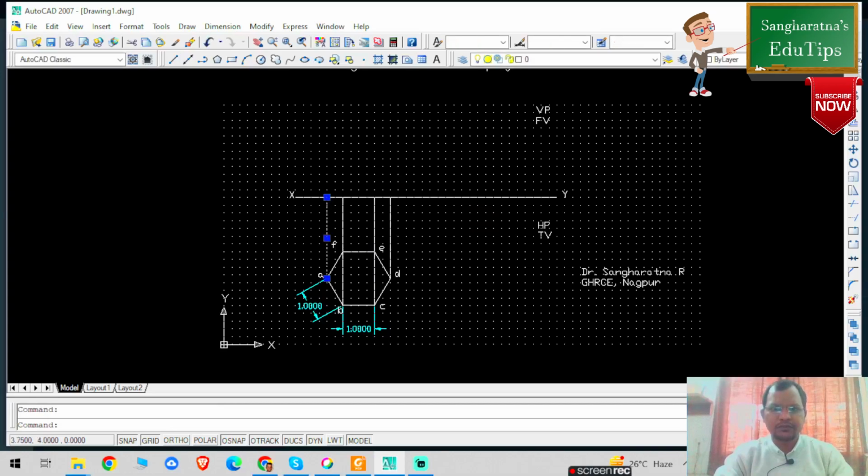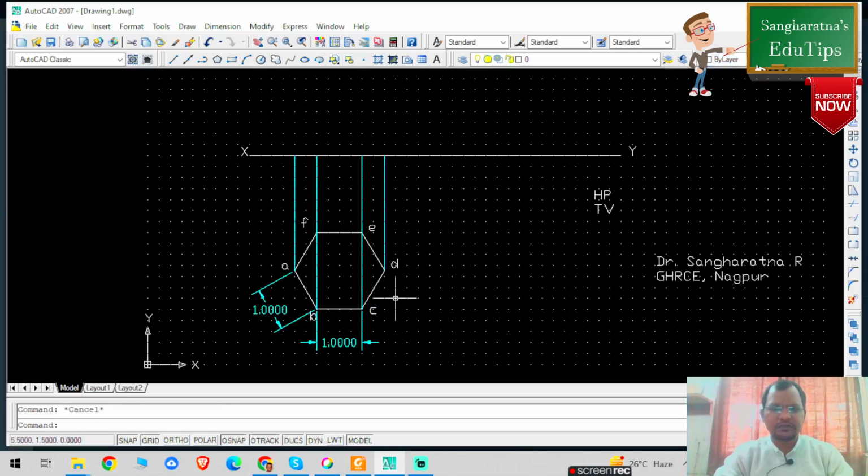So I'm going to convert this particular projection line into cyan color. So every time you need to repeat these steps. Okay, so now you can check. Now I'm going to mark the point here, because this is basically the intersection, first intersection, this is my second intersection, this is my third intersection, and this is my fourth intersection. So this becomes my true length.